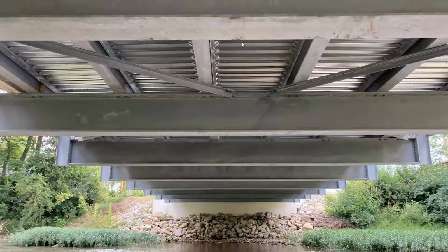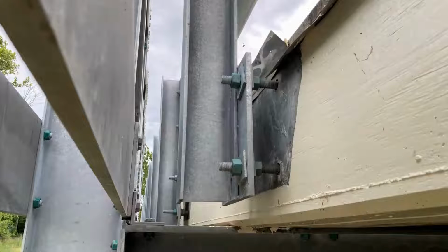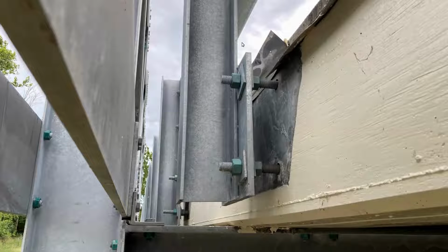Sometimes they're welded directly to the stringers, and sometimes they're supported with bracket members across those stringers. Here's a close-up view of the bottom chord plates, twin plates on the left, and then the embedment anchorage into the slab, turn down portion of the slab supporting the railing posts.